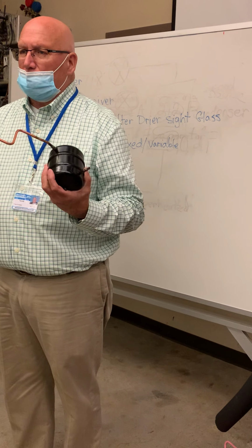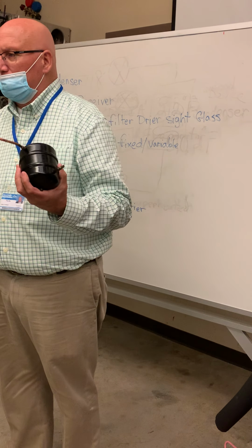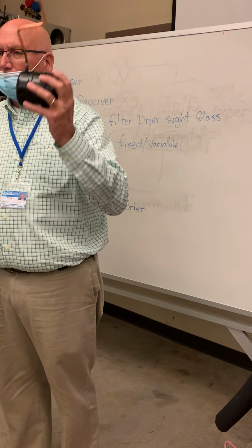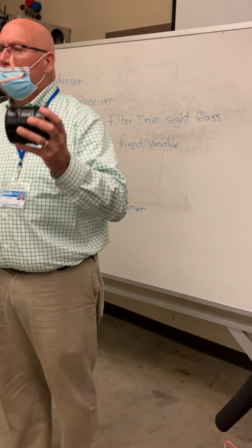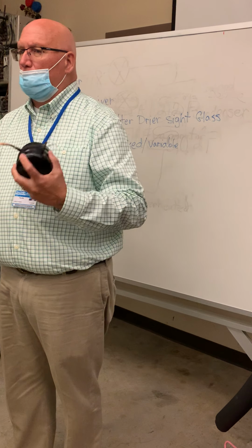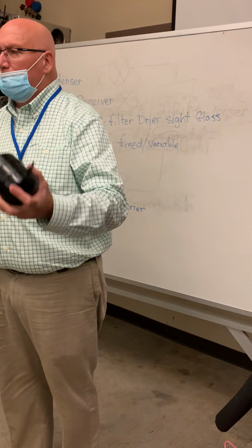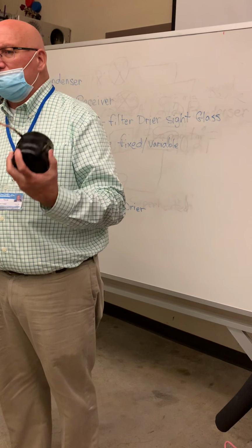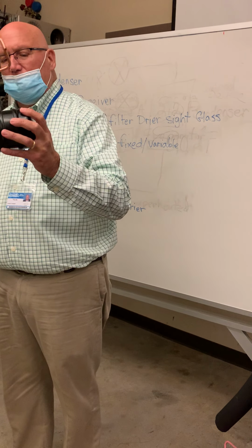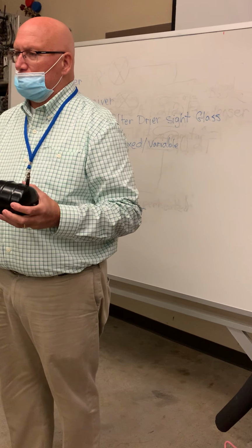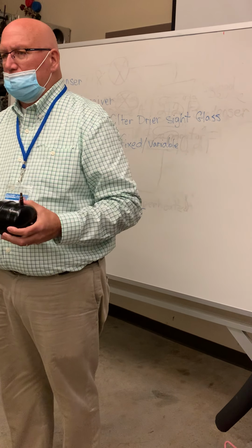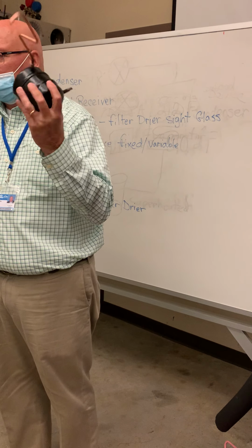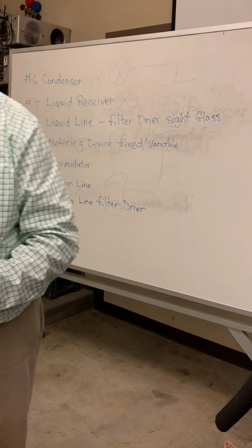It does what all cans do. It holds liquid. So this will just hold liquid refrigerant. It holds it until the system says, I need more refrigerant in the evaporator because I need to absorb more heat. So it's used in conjunction with a variable metering device, this liquid receiver. But that's all this thing is. It's an empty container that holds refrigerant.